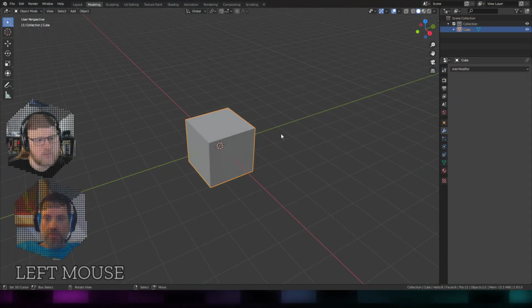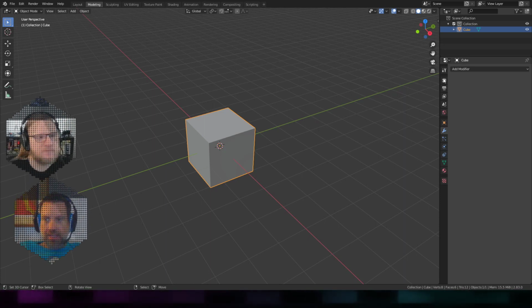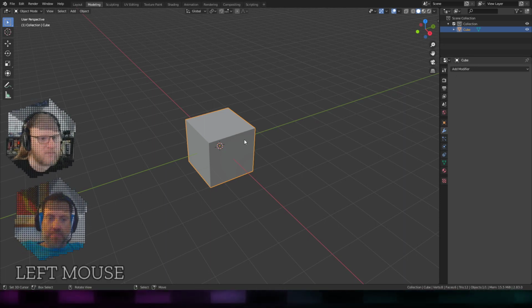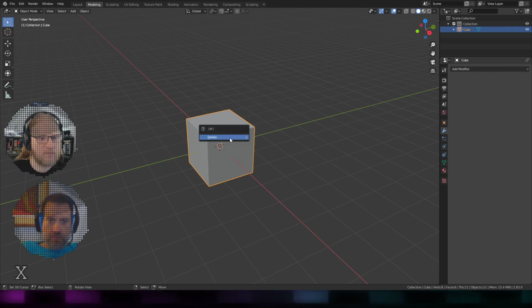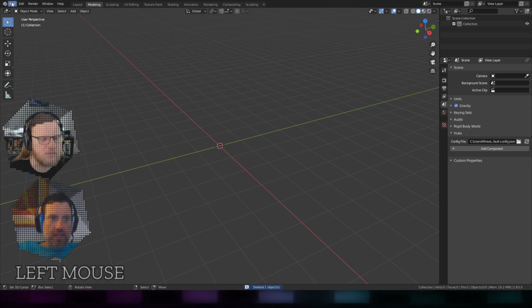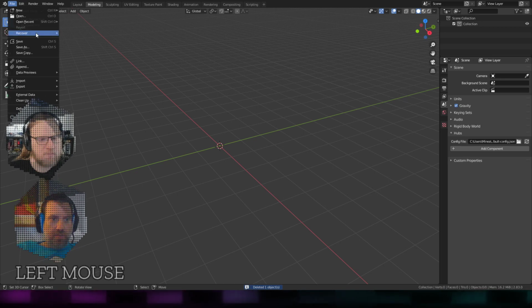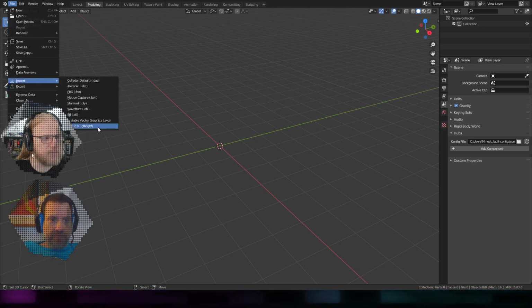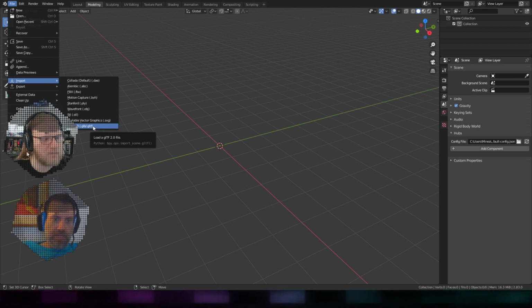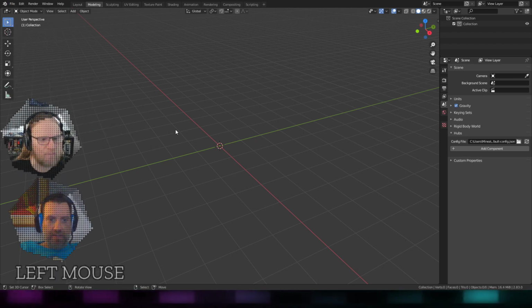Exactly. I'm going to pop over to Blender now and bring that model in. You can't just open it; you have to do an import. So I'm going to get rid of the old cube. Bye cube. Then I go in and choose import GLTF 2.0. You'll see it says GLB also next to it. Can you see this screen?